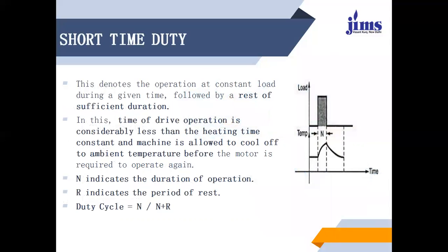Next is the short time duty cycle. This denotes the operation at constant load during a given time, followed by a rest of sufficient duration. In this, the time of drive operation is considerably less than the heating time constant, and the machine is allowed to cool off to ambient temperature before the motor is required to operate again.